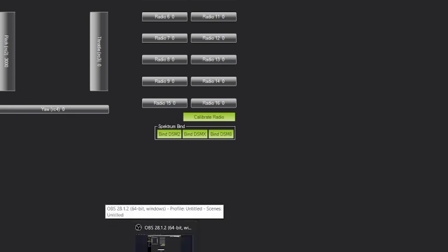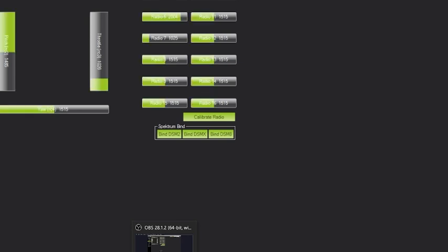Alright, so once you've done that, on this part, you'll want to calibrate the radio just to make sure that everything's working properly and that it's all going to function as you plan and get the values that you're looking for. So go ahead and fire up your remote. Once your remote is on, and if it is properly getting signal to that receiver, which the receiver should have a solid red light on it, and just having it plugged in will power that receiver as well.